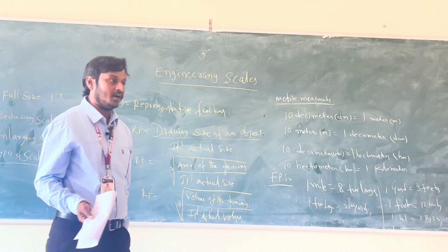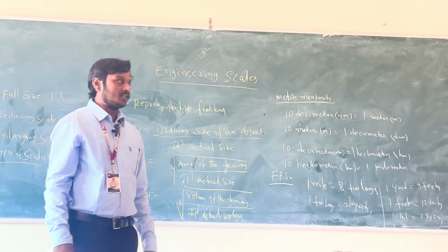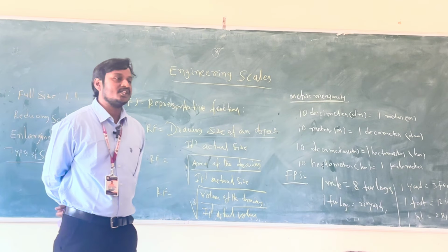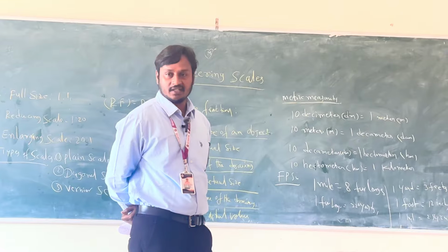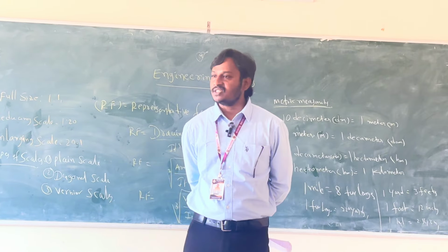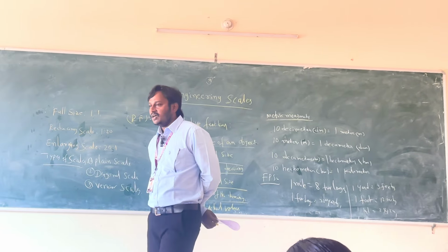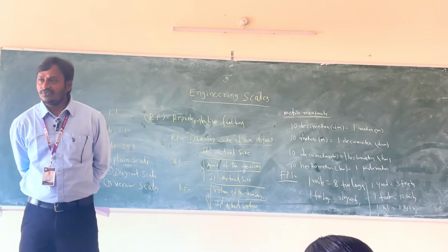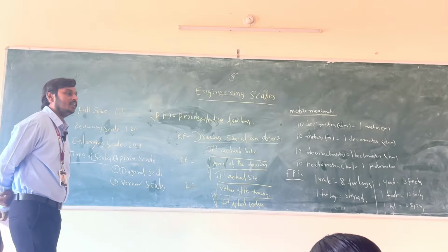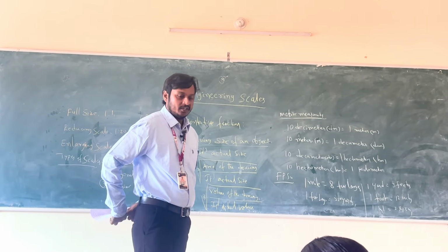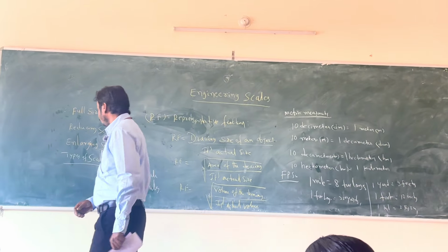Now take one problem. Already wrote the problem. What is the problem? Construct a plane scale where 1 centimeter represents 4 meters and long enough to measure 50 meters. Find the RF. Mark on your scale 36 meters. Now let us solve that problem.